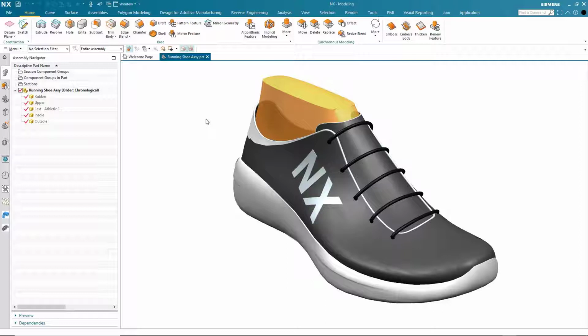In the additive design space, there's been a shift from the traditional rod and ball structures to these triply periodic minimal surface structures such as gyroid and Schwartz, and this is mainly because of the inherent properties they possess. These properties are very interesting to the additive community. The structures are self-supporting, which is a big benefit when it comes to the 3D printing process. It means that there's no need for any extra support structures.